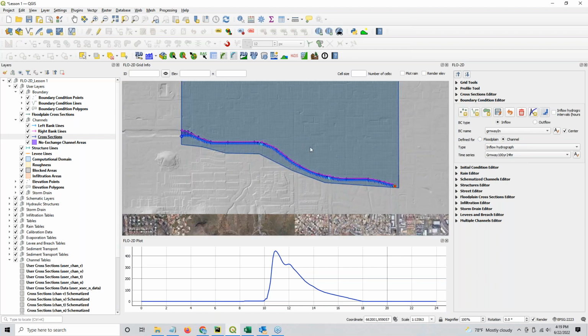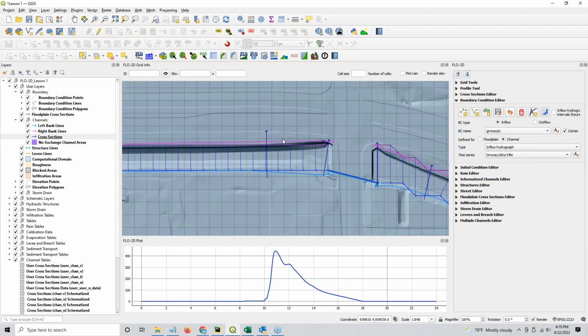I don't know of anything else wrong with channels. Oh, when you get to your overbank flow, and if you have a really small grid system and you start getting overbank flow, you might see that you start getting some instabilities with the channel as soon as the water starts to overtop. So in that case, you definitely want to increase the n values. The bank elements are probably already going to be automatically increased, but if you got like build 19 or older, build 18, build 16, you might want to just bump the n values up on these grid elements that are on the banks.